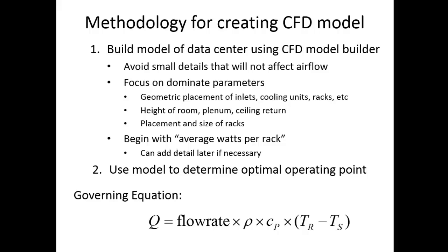So what you really want is the delta Ts to be exactly the same, because most of this other stuff hopefully is the same. You get the aggregate flow rate the same between supply and demand. Density doesn't change, specific heat doesn't change. So you can see where this turns into a relationship between flow rate and delta T for a given heat load.